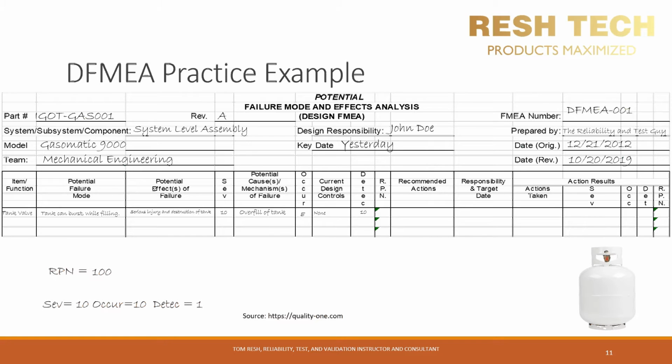Okay, getting off my soapbox, let's get back on topic here. Let's go ahead and plug our RPN value into the table. If you're using Excel and you are lazy like me, do yourself a favor and create a formula for your RPN column to auto-calculate your RPN value based on your severity, occurrence, and detection. Work smarter, not harder.